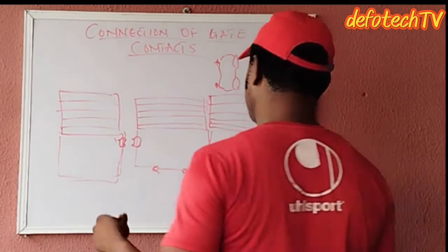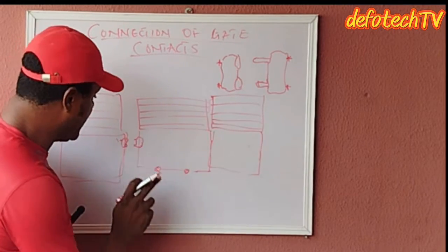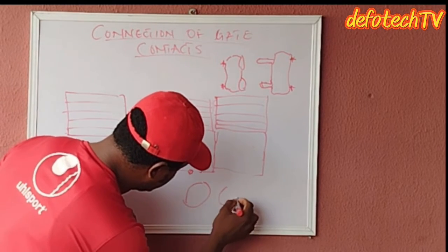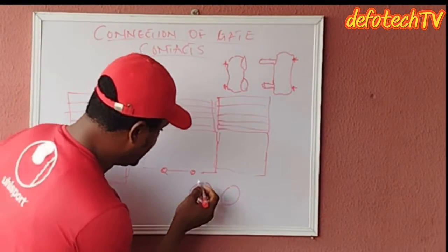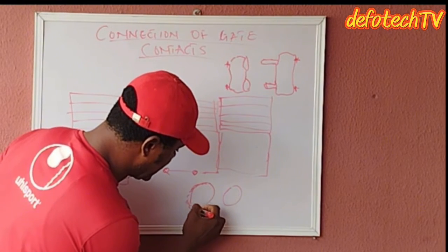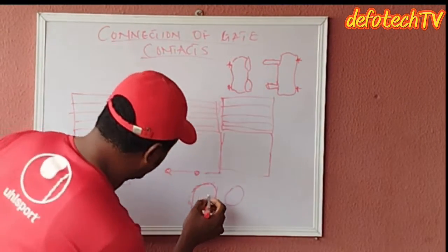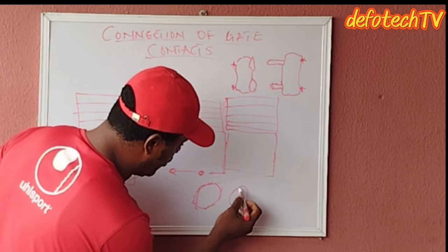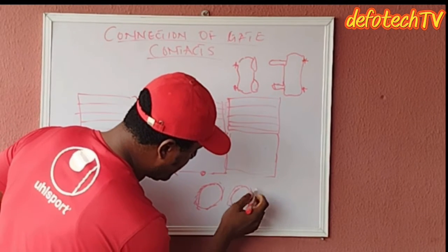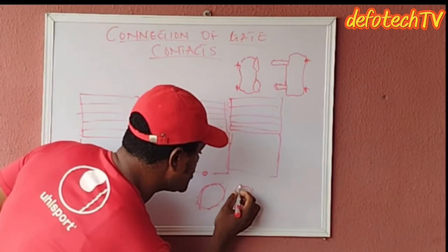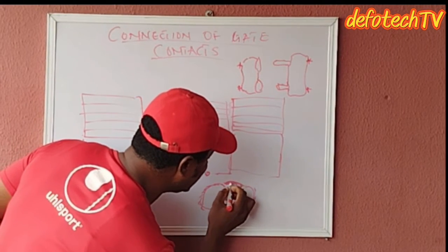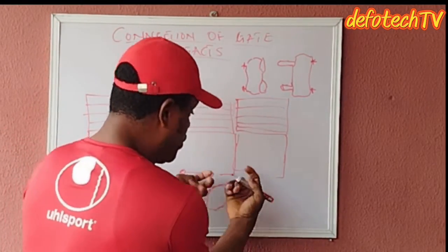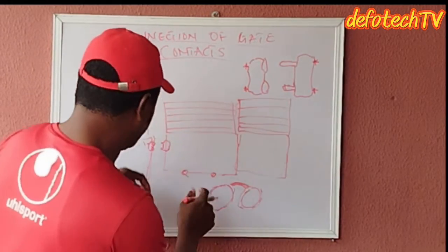If this spring is pushed in, it becomes normally open. The way it's designed, let me do something like this. The way this inner part on the female is designed, inside these circles there's a kind of conductor around the circle, not the one going inside. There's one that moves in and has contact with this outer one. The moving part goes in, immediately has contact with this, and this one inside is linked inside. So it is only when the spring pushes this one back and touches this that it closes this contact.